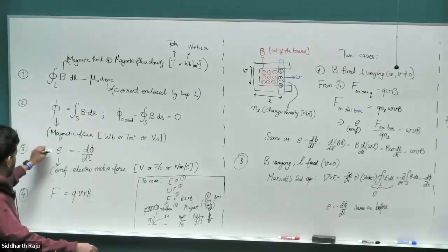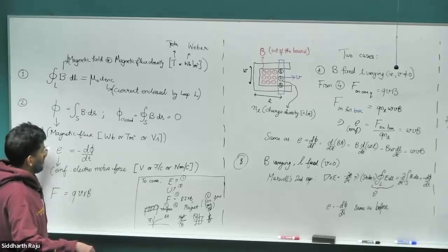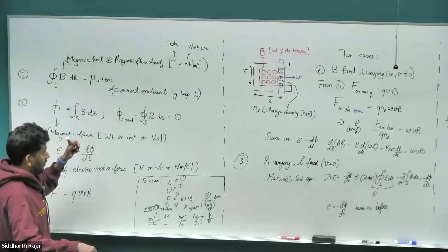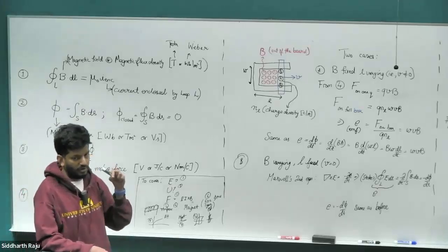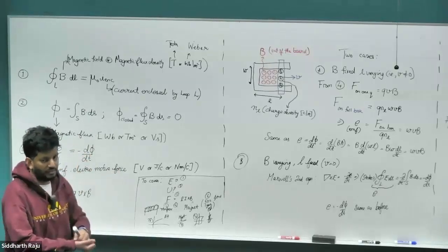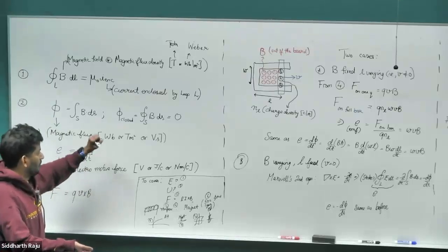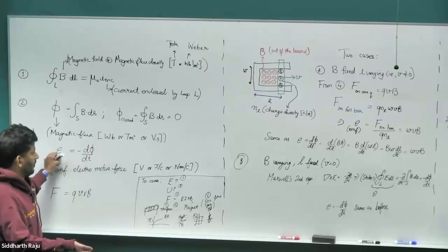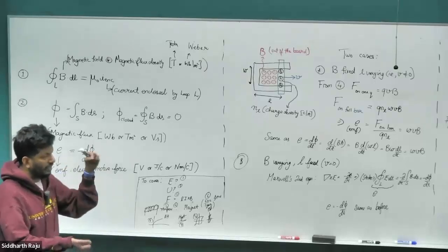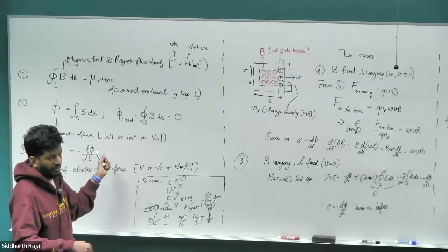So the last one that we simplified was Maxwell's second equation, which is basically Faraday's law: the EMF generated across a coil is proportional to the rate at which the flux is changing through the coil. And we made sense of what the derivative means, which is what Lenz's law states. If you were to close the circuit where the EMF is generated, it would create a current that would try to oppose the changing flux outside. That's what the negative sign means.